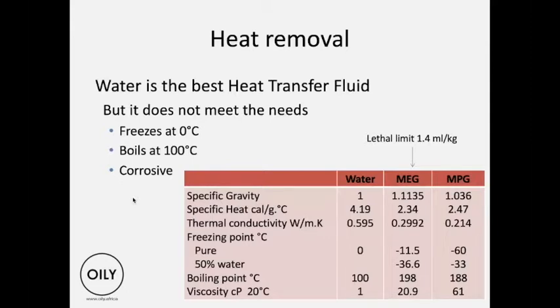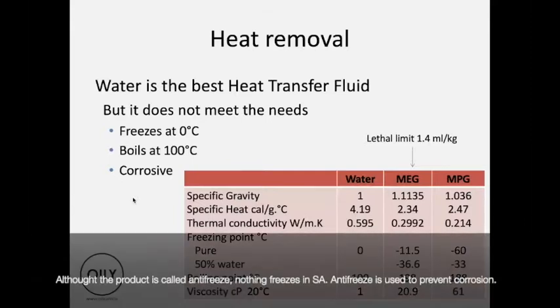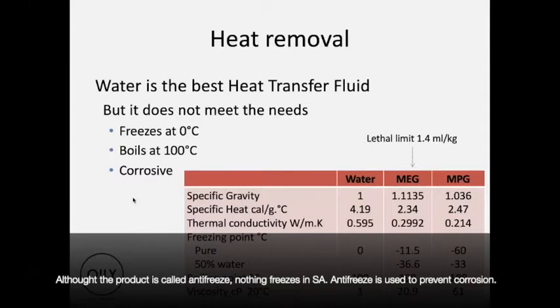But in South Africa, the major function is to raise the boiling point. Freezing is not so important. Corrosion and rusting matter. That's probably the biggest misconception in the South African market, because when you call it antifreeze, nothing freezes here. We don't need it. Yeah, but that's why we need it.